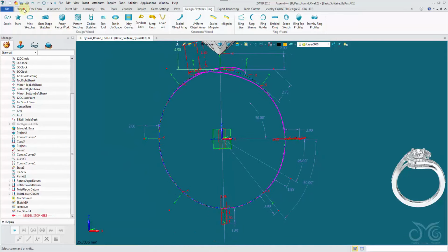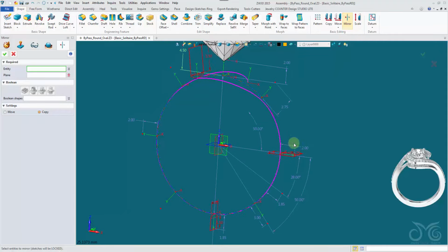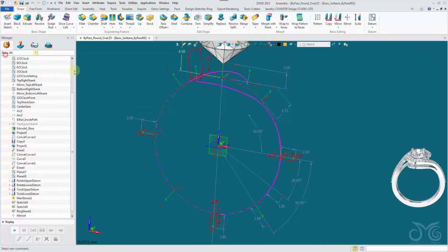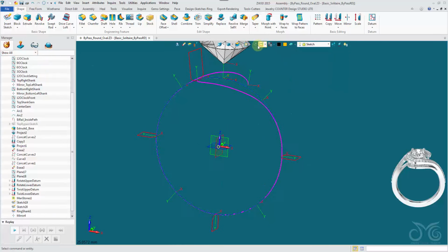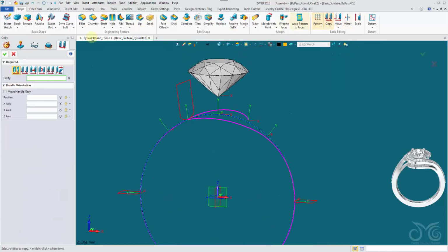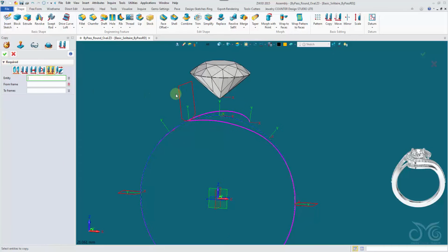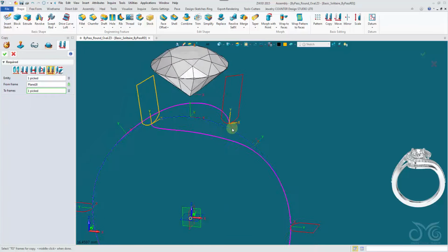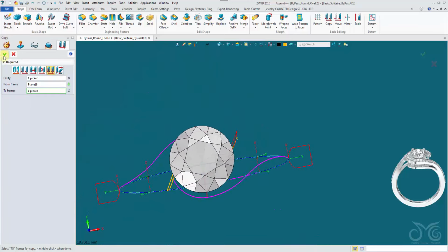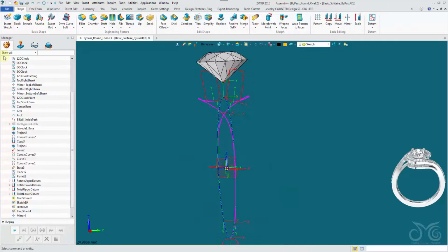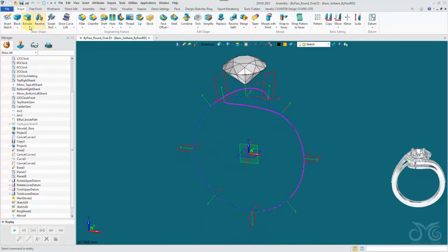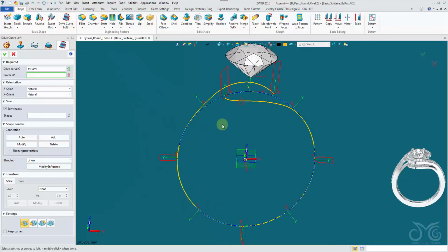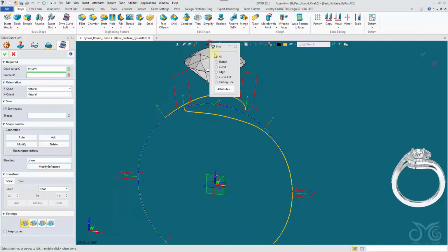Now I'm going to the shape. I'll mirror first of all this sketch over to the opposite side. Let me hide these dimensions. Then I'm going to copy frame to frame this sketch from its datum plane to the other side. Then we can come in with a drive curve loft, driving curve, picking the sketches,